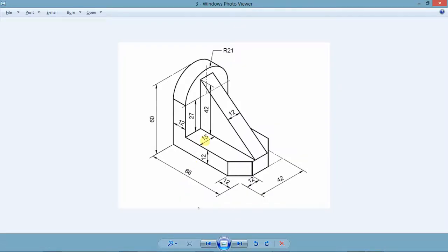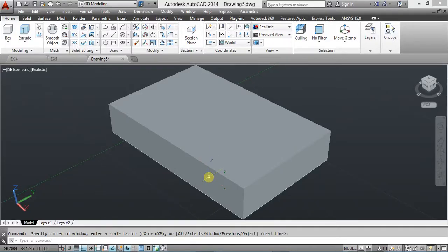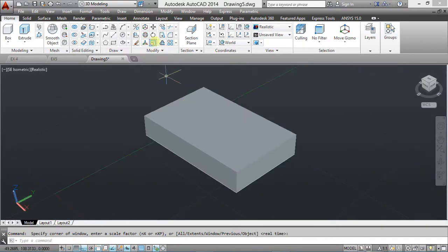Now I'm going to chamfer it. I just stand 12 this side, 12 this side. Do chamfer, not fillets, you get chamfer from there. Select chamfer, it asks you to select the first edge.